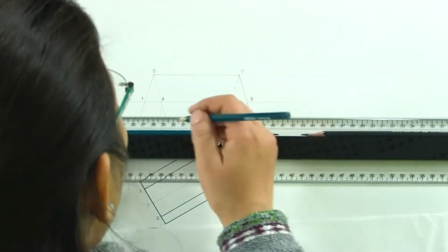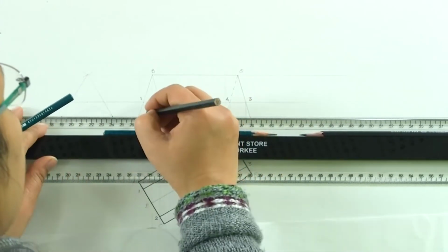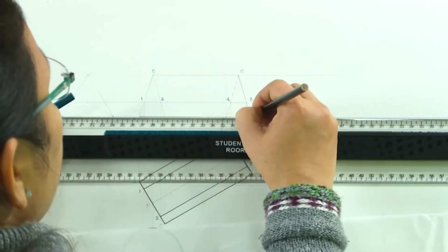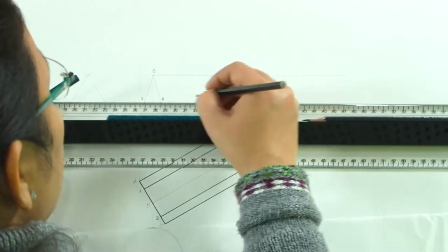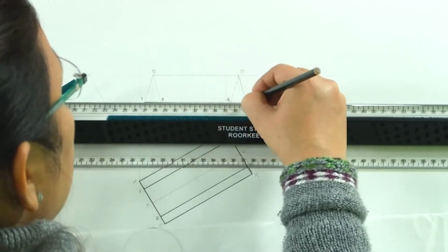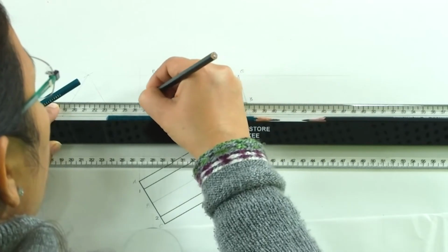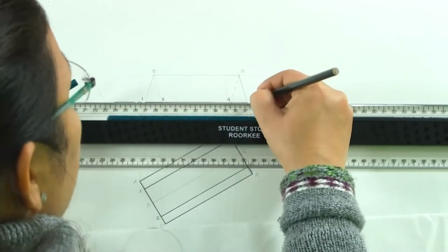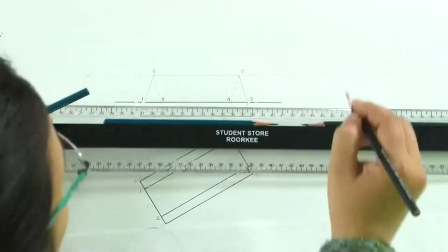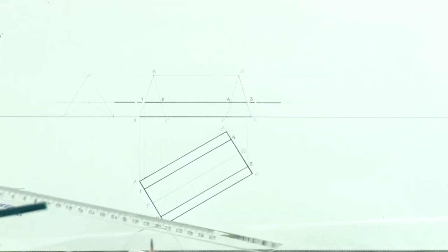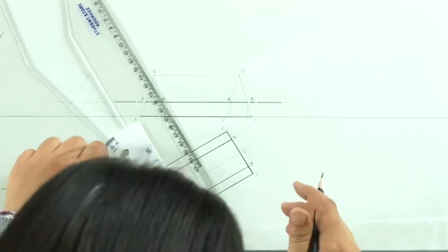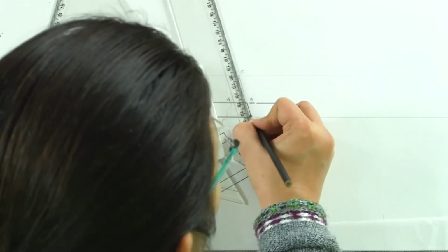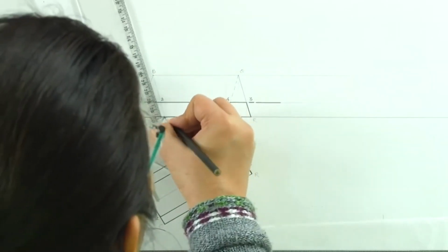Let us draw the front elevation as well. This is the section plane. Don't get confused by the axis, because when we draw the axis, we draw a long dash and a dot, while when we draw the section plane, we draw a long dash and a small dash.